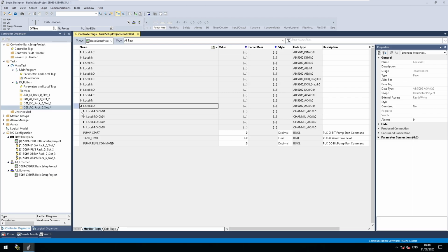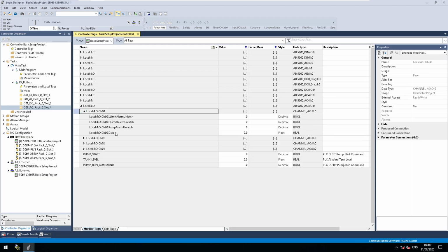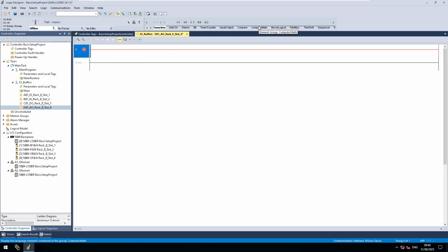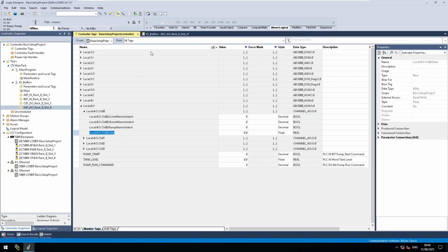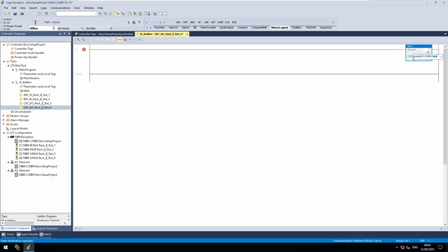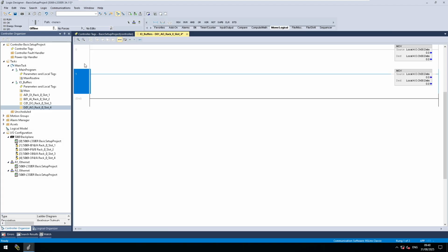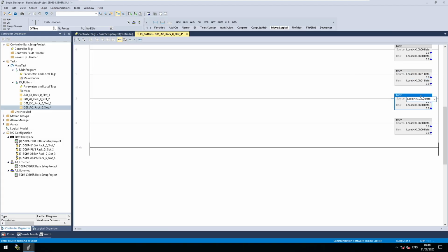So now for our analog output, copy the data point again. And here we'll need a move. So for my analog outputs, I'm going to have a speed command that gets sent to the pump. So I'm just going to call this pump speed.